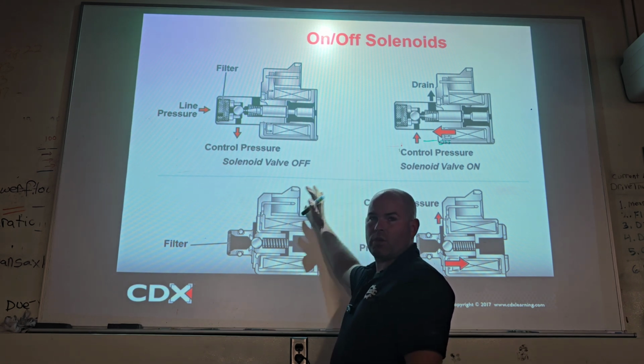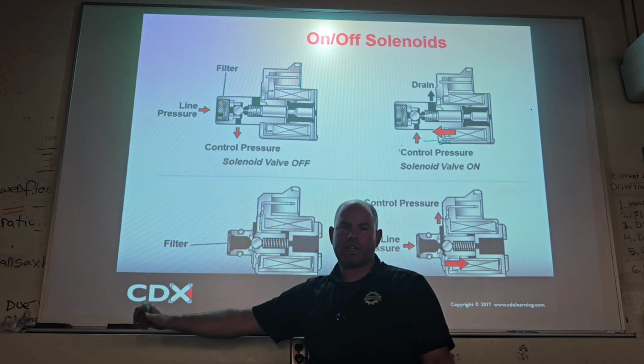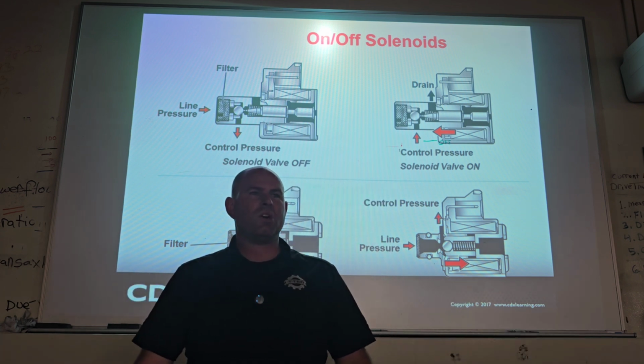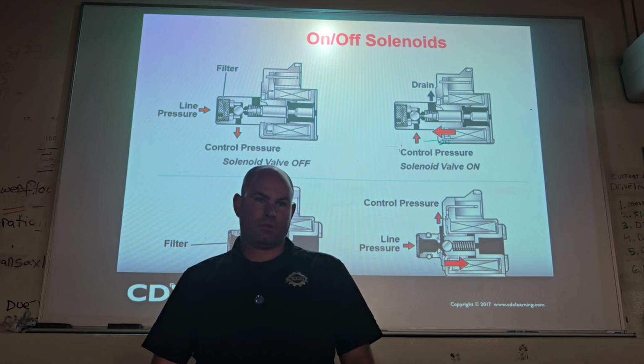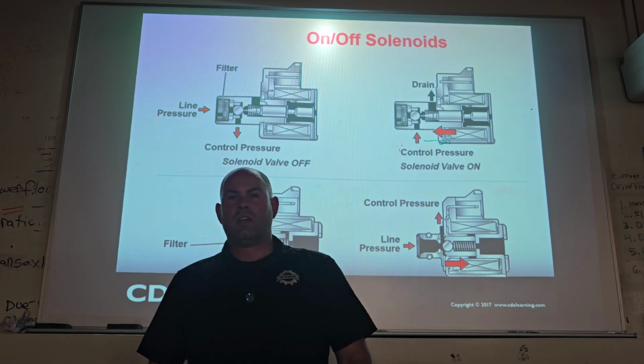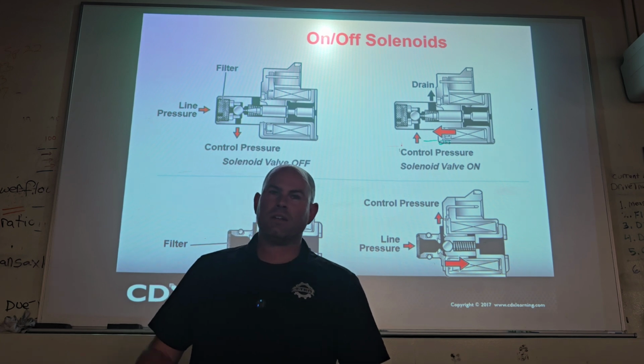You could have a shift solenoid that is electrically fine, but when it goes on and it tries to flow fluid, it just doesn't flow fluid. So what codes is that going to set? It might not set any codes. It might not shift. It might have funny issues, but it might not set any codes. It could be a little tricky. Renee, go ahead.